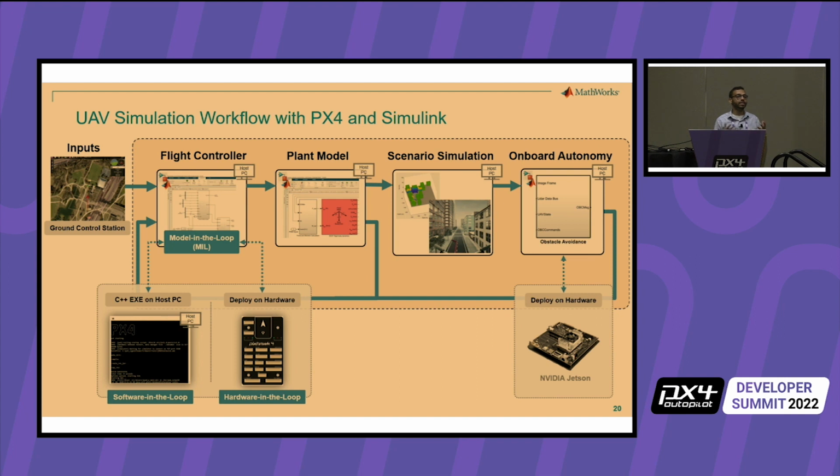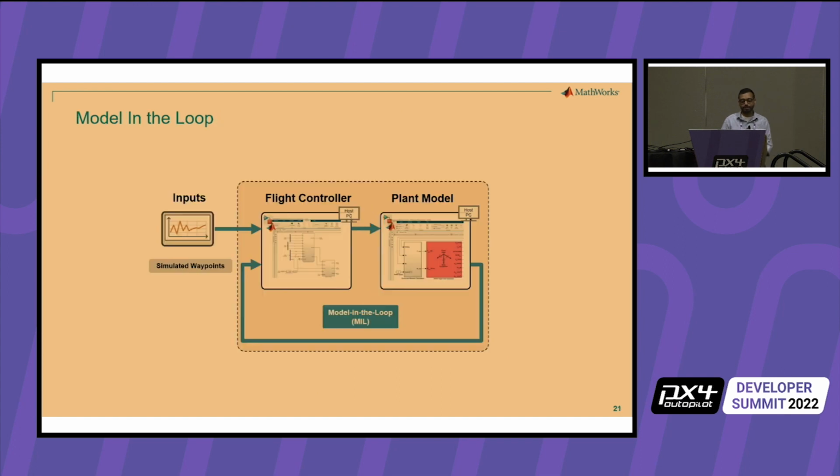And then finally, we can take that generated code and deploy it directly onto the Pixhawk. It's going to be hardware in the loop, so all the sensors will be disabled, but we'll simulate the sensors. But you can guarantee that your code's running. The flight controller is actually running it as a processor on the PX4 itself, on the Pixhawk itself.